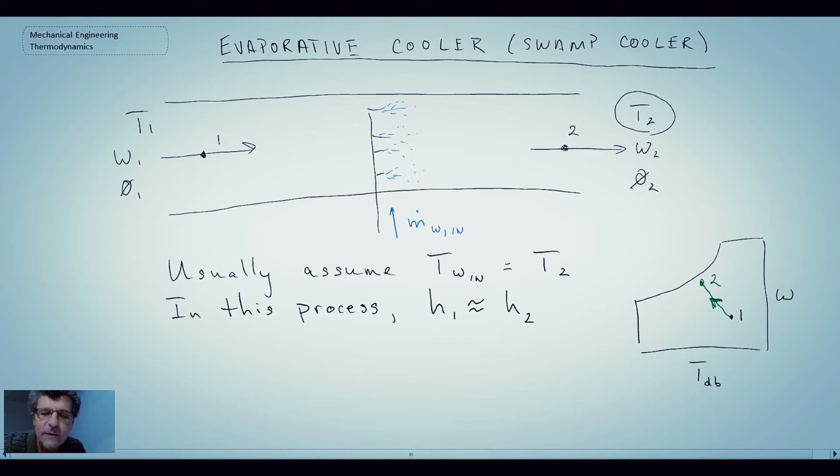And then again, what you do is you go through and you do your air balance, you do your water balance, and you can apply the first law, but you calculate it using enthalpy in the way that I've shown you here. So that is the evaporative cooler.